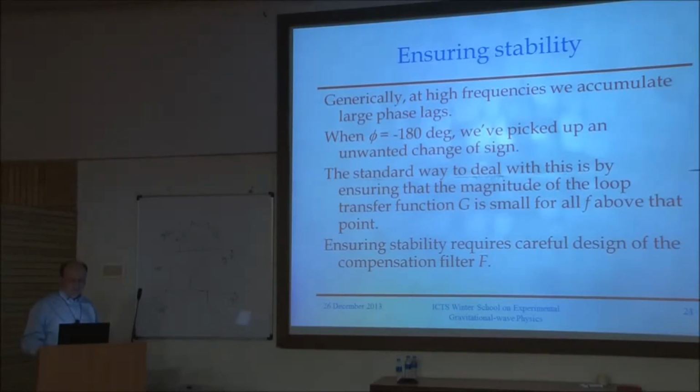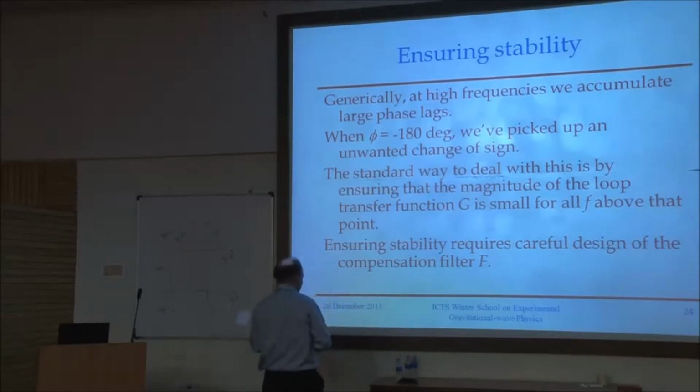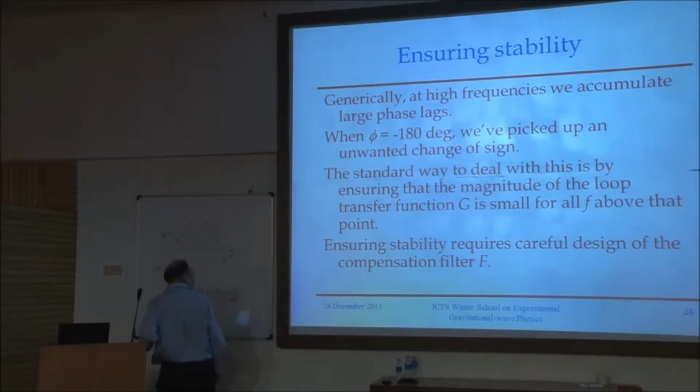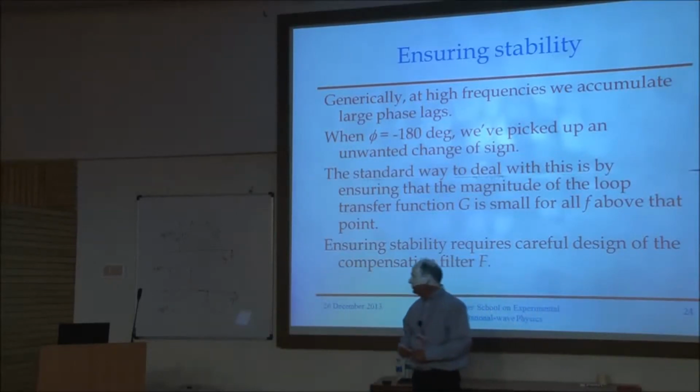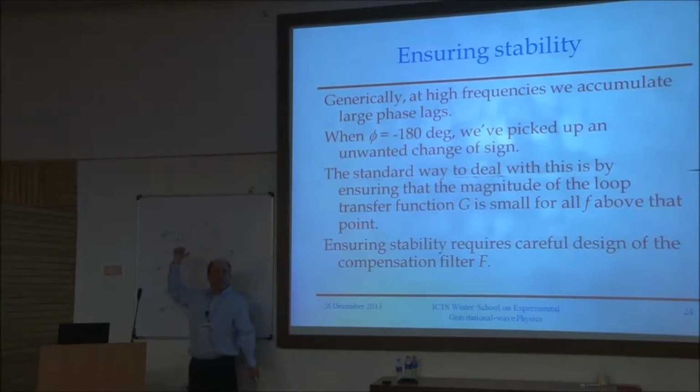Now, here are some words to remind you of what the real limit actually is. When I make this active vibration isolation system, my actual loop transfer function is more complicated than this. And the most important problem that happens is that in my mechanical connection somewhere, when I'm trying to push, suddenly I encounter a resonance that I didn't model. Some part of the actuator is resonating and can grow another resonant peak.